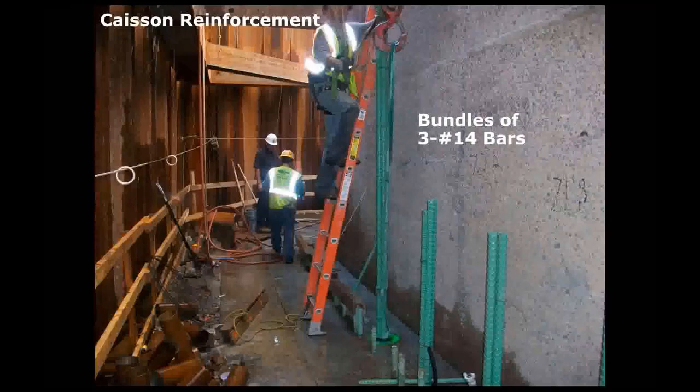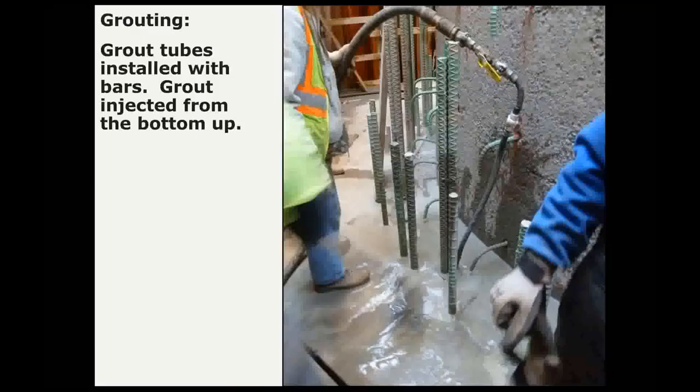Once we did get the holes cored, we were lowering in bundled number 11 and number 14 bars down those holes. And since the length of some of those holes exceeded the length of bars we could get, we were also using mechanical connectors. We had to stagger those mechanical connectors to make the bundle tight. We were lowering those down the holes. With the bars, we sent grout tubes down the holes so that when we installed the grout in the holes, it got pumped in from the bottom up.